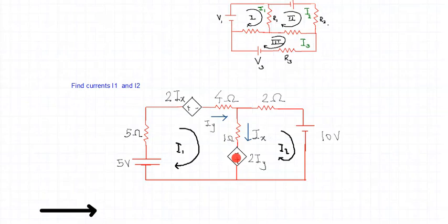Now the next thing that you do is look at what is being assigned here. This dependent source is a function of Ix. It means that it is a current controlled voltage source. Similarly, what about this? There is 2Iy. So this particular voltage source is also a current controlled voltage source. This is the way you identify the type of the sources which are given in your network.